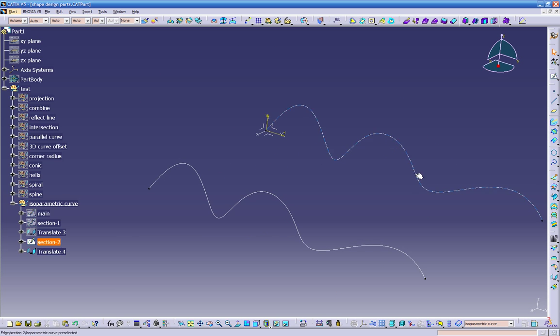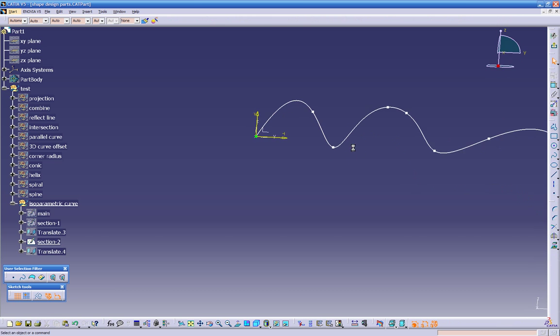If I edit this shape right here, which is this sketch, it's automatically going to update my translated sketch because they link together. So see, I'm going to hide this right now, and basically this is what I'm going to edit. But the moment I edit this, that's going to update my translation. So I'm going to double click.